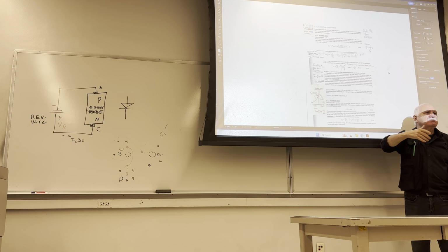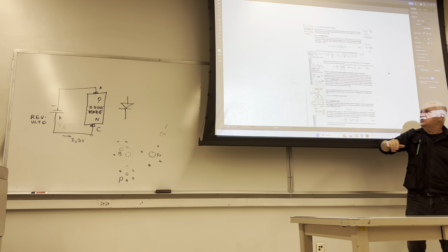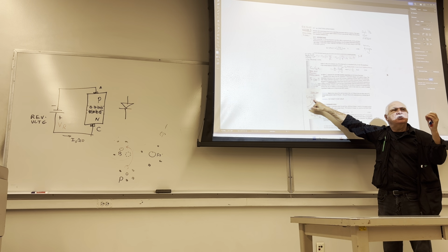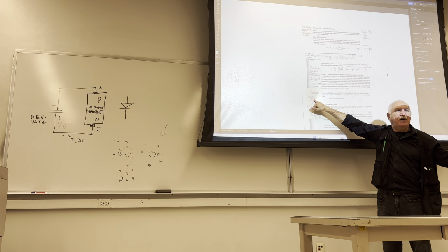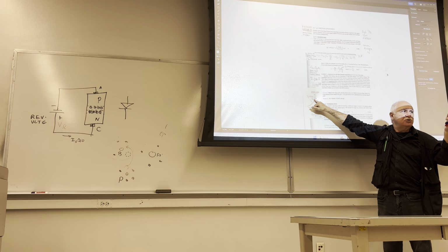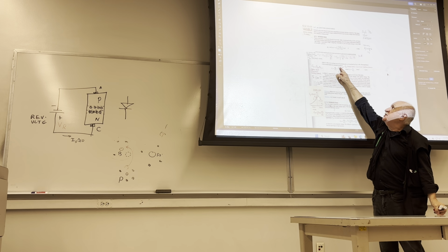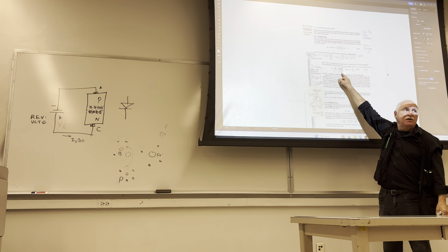What is the range? Typically, the manufacturer will give you that information. It's known as the zero bias junction capacitance. So they will tell you that you have here a zero bias junction capacitance of 150 picofarad. So you know that, the top of the equation. Phi is typically half a volt.